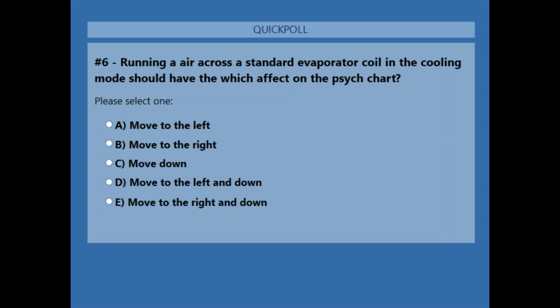Plus, cool water is what's going to be coming from my city water supply. So there's no reason to heat the water up first to begin with. That would just be an energy waste. But I will have a slightly different benefit if the water is in fact cooler. The examples that we had shown assumed the water temp was the same as the air temp on the psych chart. But there would be a benefit to using cooler water if I am doing evaporative cooling.